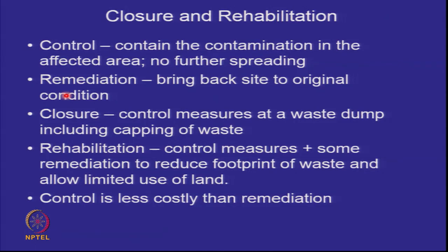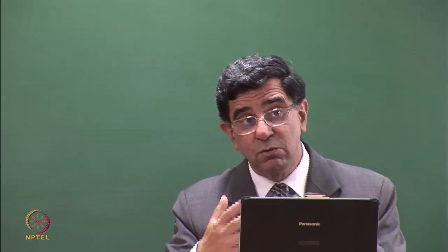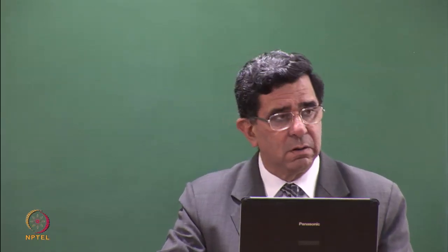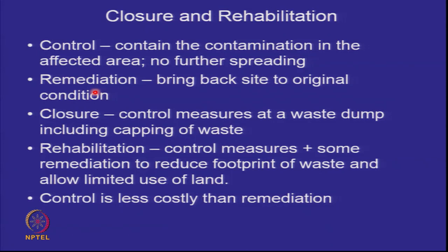Remediation is the other extreme. Remediation is I want to bring back the site to its original condition. I have to make the waste vanish. Even if I remove the waste, there may be contamination below. I have to remediate that. Suppose the groundwater has got contaminated by some chlorides, I have to remove those chlorides. So I have to bring back the site to the original condition. Extremely expensive, not often doable. But that's what you mean by the term remediation. People tend to use words interchangeably, but that's not the case.